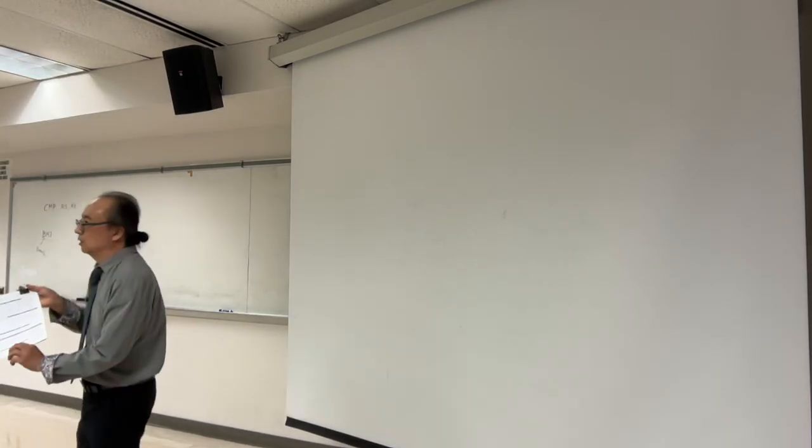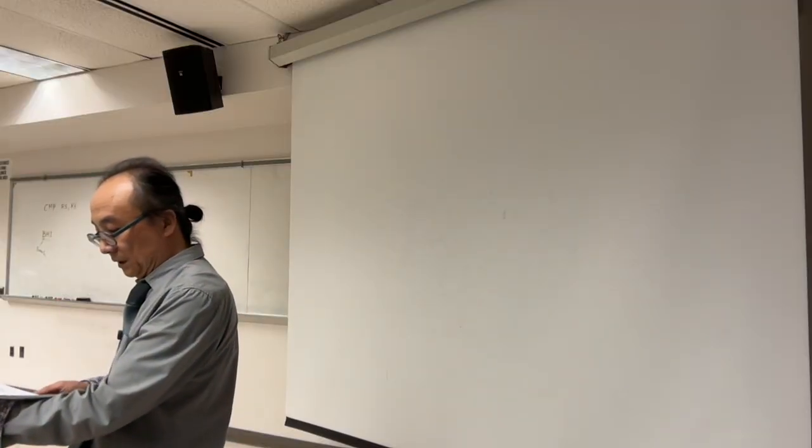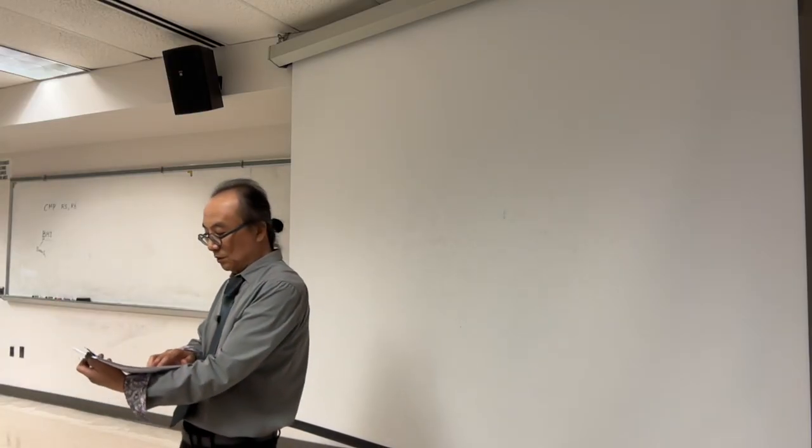Then we have to do some actions, right? Depends on the result. And the first one was BHI. So the first letter is for the branch. The next two letters are going to be from the condition. So this handout, while I was preparing for this lecture, I made this. You will see as the first page, data processing, and we have instructions like XOR, sub, add. If you move down, there are shifts, move, LSL, LSR, and ASR, all of those. There's a CMP as well, which is compare.